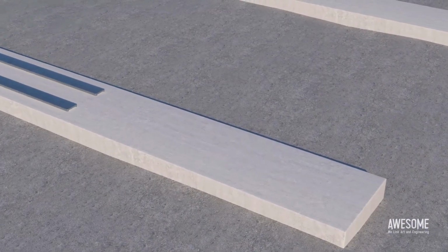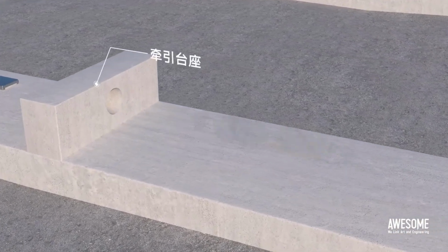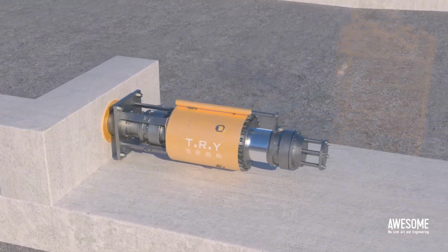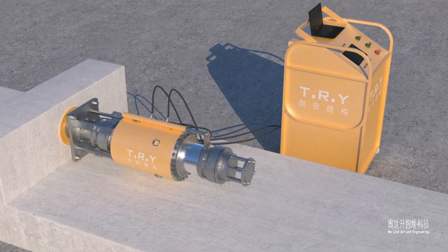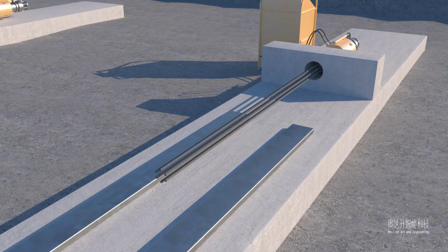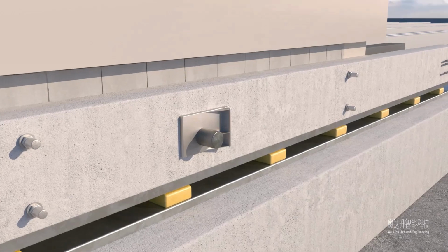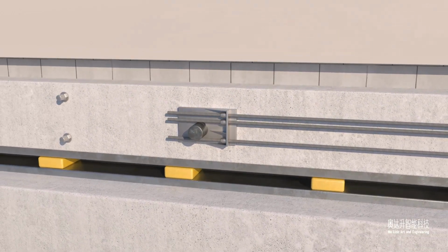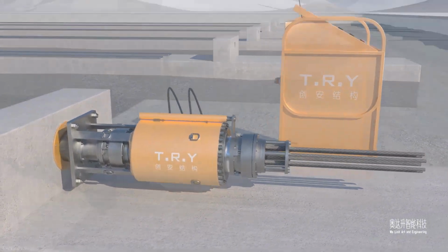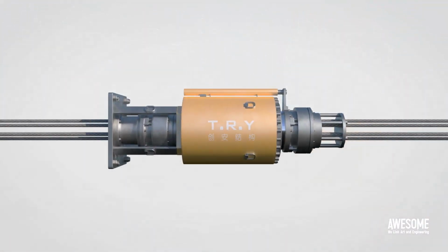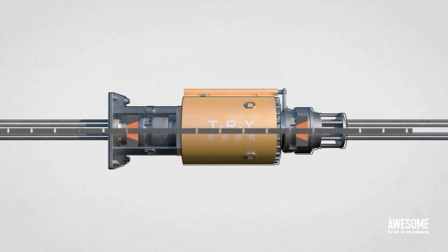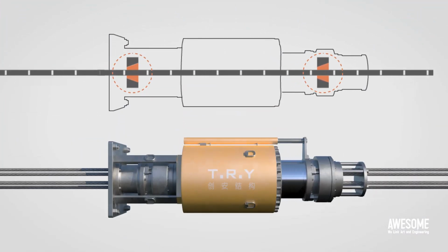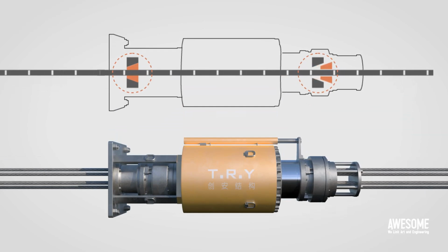The power system adopts a tension type. The transmission of tension is completed by setting a traction pedestal, a through-type jack, a PLC hydraulic synchronization system, a steel strand and an anchor device. After the preparation work is completed, the overall translation of the building begins. The displacement value of each translation of the building is controlled by the jack stroke, and the operation is cyclic until the design position is reached.